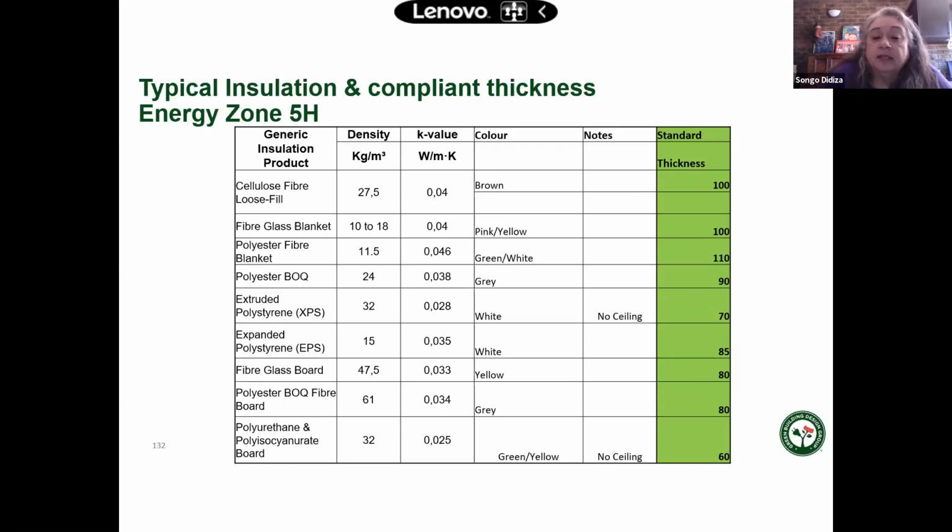In the main interior of the country and in the Western Cape, it says that you need 135 mils of glass wool. And what we find is that the polyesters are saying, okay, you need 135 mils of polyester as well, like they're saying you need 100 mils of polyester. No, it's not about thickness, it's about performance. And every material has a different performance. So you have to look at the system to see what it is giving you.